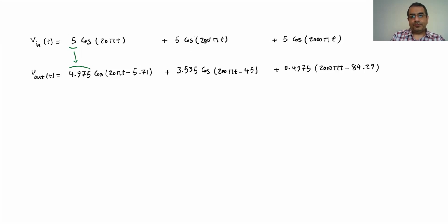When we come to this one, which has a frequency equal to the cutoff frequency, you will see that the 5 changed to 3.5, and the angle changed by 45 degrees. So this is where we are actually sitting on the cutoff frequency.